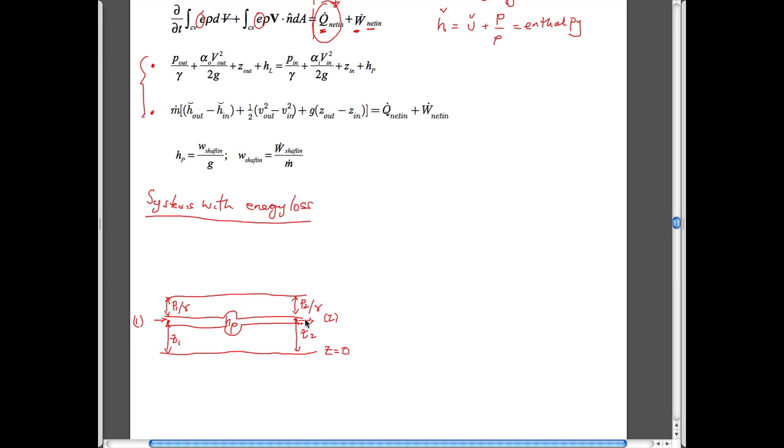It's a tube, let's ignore the pump for now, but it's a tube that has constant cross-section. So we could imagine that the velocity in this would also be a horizontal line, right? Because it's not changing area, and continuity tells us that this would be the same. So it's V2 squared over 2g, and V1 squared over 2g.